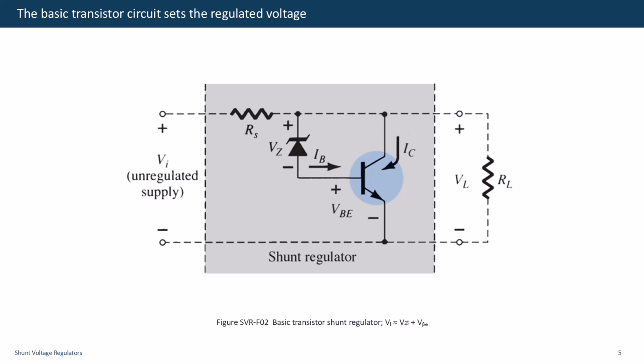If load resistance decreases, load current tends to rise and output voltage tends to fall. The reduced transistor base drive makes the transistor shunt less collector current, leaving more of the source current for the load. This action supports the output voltage despite the heavier load.